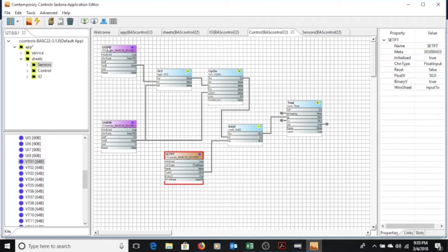So remember, the common does not mean neutral. The common does not mean neutral. And one more time, if you look at this screen when I'm talking to you, pay attention to what I'm telling you, the common is not neutral. Okay? So it's how all digital commons, relays, all other functions of switching actually operates. So you have to pay careful attention to the way in which you wire something. Just one not wired correctly can wreck all of them. So I'm going to save this to the controller.